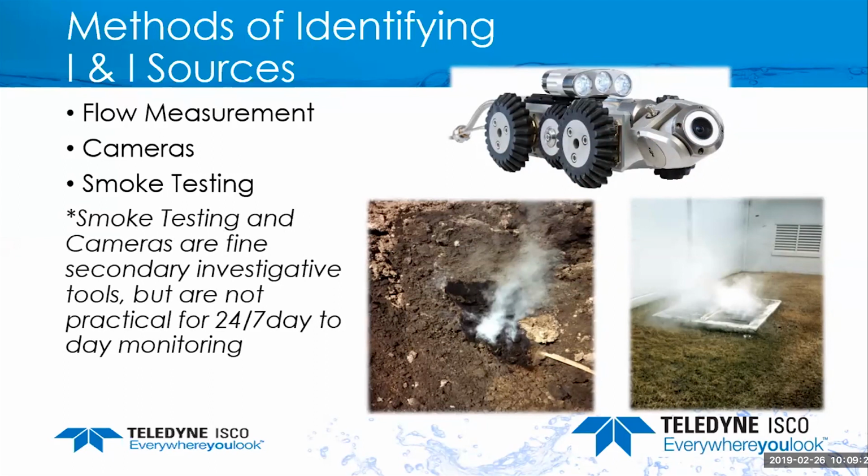You wouldn't use this for flow monitoring, but once you've determined what section of pipe may have a problem, you can go a little more in depth with the camera or smoke to know exactly where we're getting the problem from. If there are cracked pipes or drain pipes from houses tapped in the line, you're going to see smoke coming from the house or through the ground.